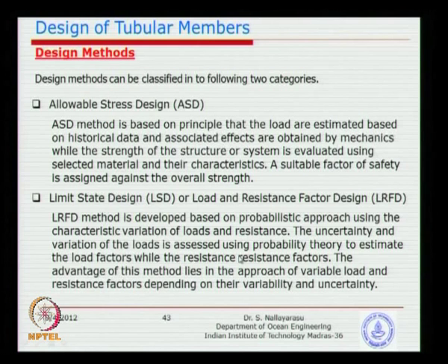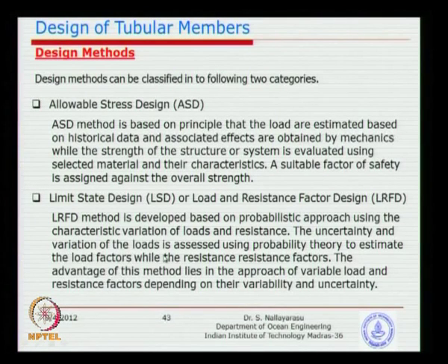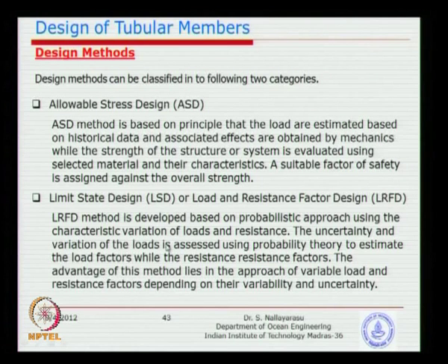So, once you evaluate that, you look for a particular parameter to be multiplied, because this is a variable loading, or if it is a non-variable load, like it is not going to change for sure, but how sure, whether it is 100% or 99%. Now, if you say 99%, there is a risk of 1% exceedance. So, should we design for that 1% risk, or should we design for 100%? That means no risk. So, depending on the risk that you would like to take, you could possibly adopt slightly increased load factors. Whereas, in the allowable stress method, we do not look at it that way. We design for a load which we do not know whether it will exceed or will not exceed.